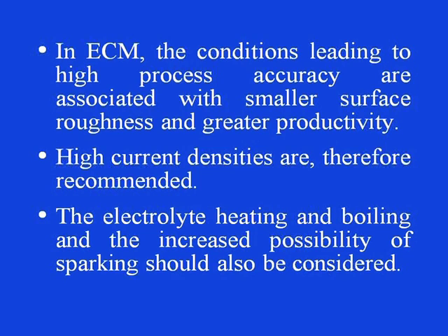In ECM, the conditions leading to high process accuracy are associated with smaller surface roughness and greater productivity. High current densities are therefore recommended for higher productivity. The electrolyte heating and boiling and the increased possibility of sparking should also be considered.